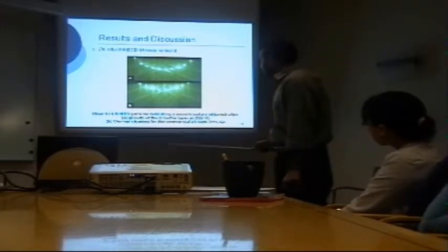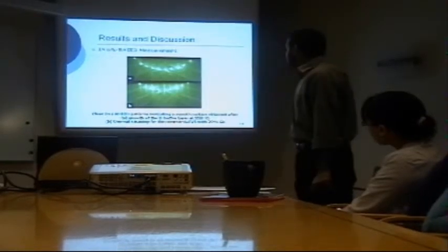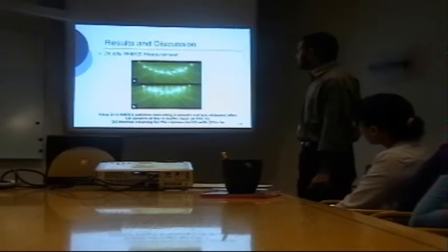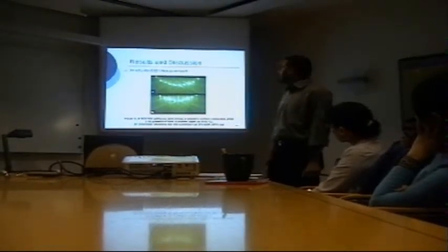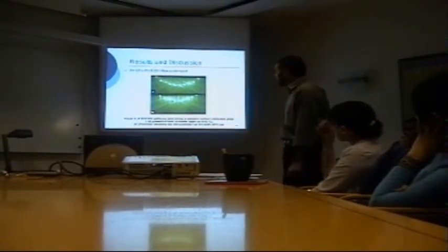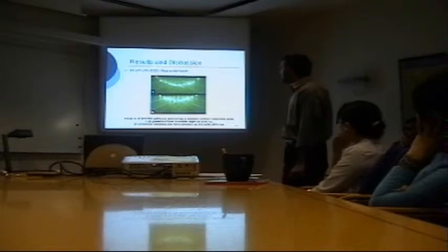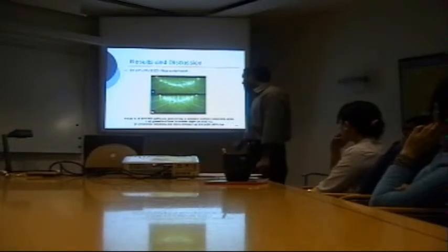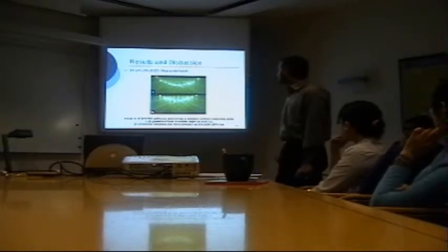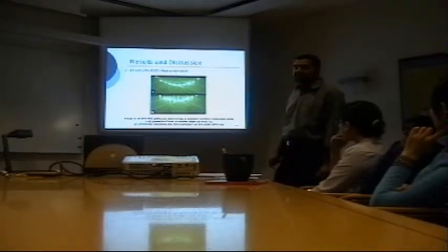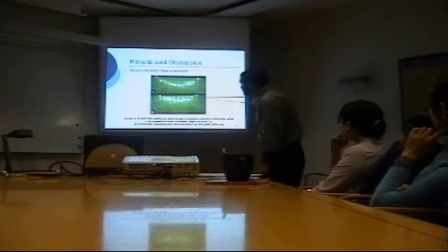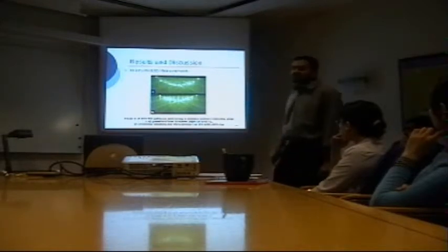In figure B, we can see the RHEED pattern taken from the surface of a commercial virtual substrate with a germanium concentration of 20%. This pattern was recorded after the thermal annealing of the surface, and we can clearly see the 2x1 pattern, which indicates that the surface is smooth, but we can still see the streaky pattern that shows the presence of 2D roughness on the surface.